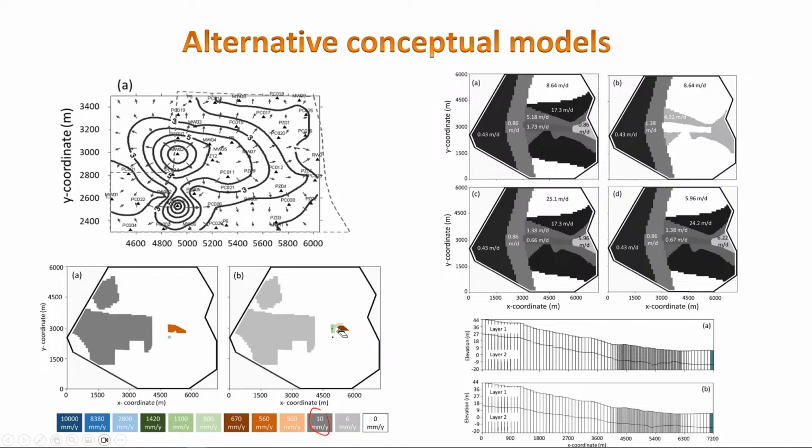For the subsurface, based on the data we have, one could conceptualize it like this. Another groundwater hydrologist might conceptualize it like this, or this, and you can have different conceptualizations because you don't have a unique interpretation for your data. We are also uncertain about the layer thickness, so it could be that small based on some evidence we have, or it could be that large based on also some evidence we have, and we don't know which is which.